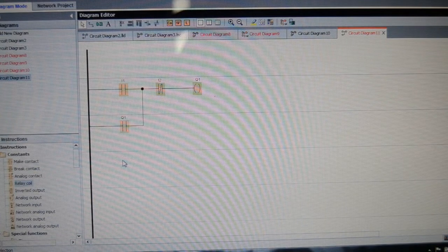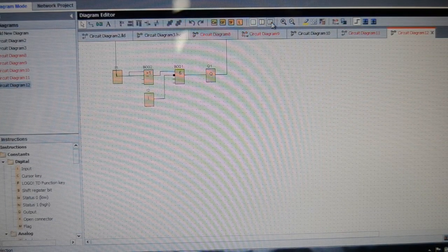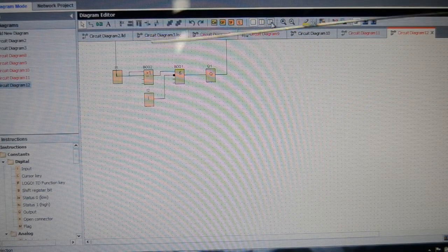Okay, so how does this influence what happens in function block diagrams? I've got rid of the second line, so we've just got our seal-in circuit. I've got rid of the simulator, and I'm going to convert this now to a function block diagram, and you'll see why it is worthwhile being aware of exactly how to produce things using ladder programming. So there you have exactly the same thing using function block diagrams, and as you can see, its complexity is much higher. So these two lines going straight up are actually linked along the top, although it doesn't show it. This is a continuous loop.